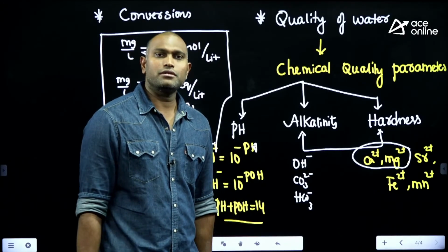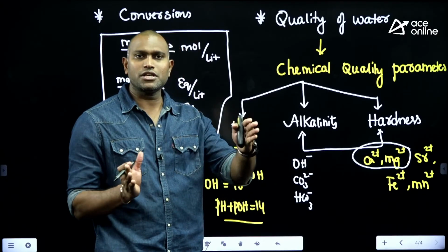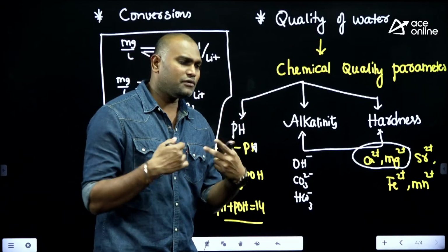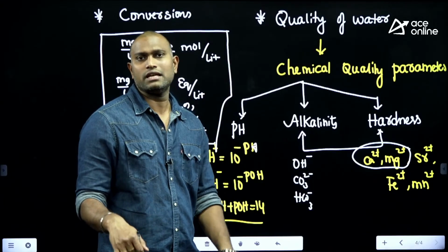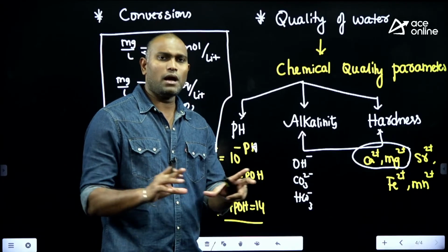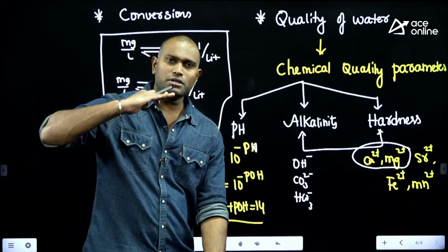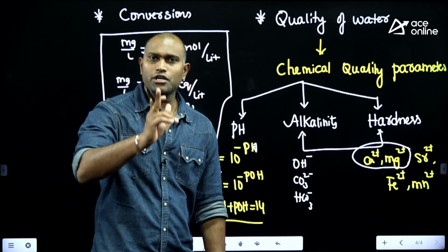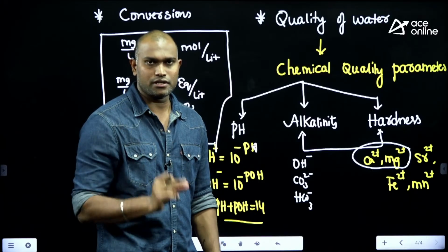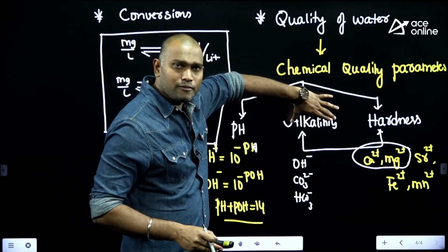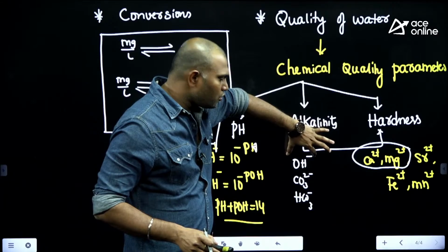In examination, they'll give you ion concentrations of various ions. I'll give you Na+, which is sodium, I'll give you sulfates, SO4 2-, I'll give you chlorides, and so on. Though I give 10 ion concentrations, you need to be aware of who is really responsible for the characteristic. If I say alkalinity, then the alkalinity is due to whom?